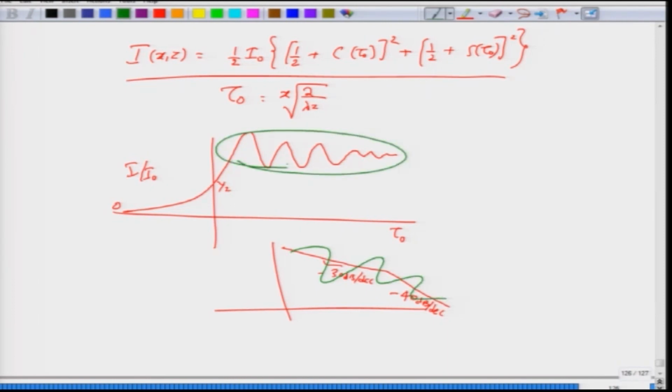That is, as you move up and down on the building side, at a given z, as you move the receiver antennas or your mobile phones up and down, you will see that the total amplitude decreases and increases. So, there is a variation in the amplitude, and this variation continues with smaller amplitude as you move away from the building. That is why in certain areas you suddenly see that you can hear the other person speak very well, and at certain areas just behind the building you cannot hear, and as you move away slightly you will see the effect of this shadowing.